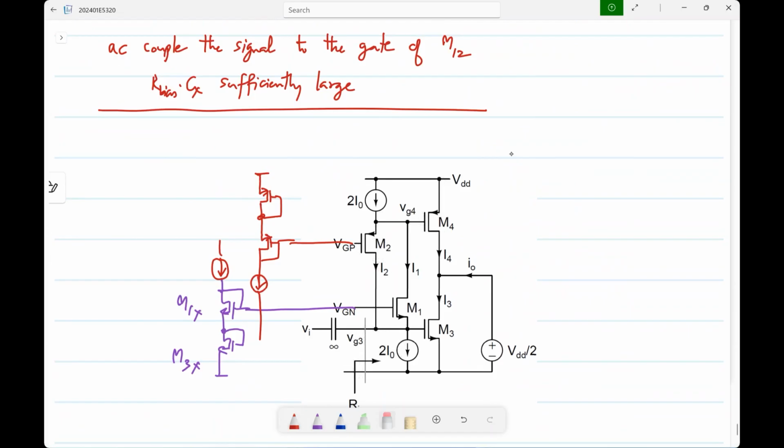I'll continue from there, but I would say this has now fallen out of favor because it's not easy to accommodate all these transistors in a 1 volt or a lower supply voltage. But when the supply voltage was higher, this was used quite widely. This was actually reported in one of the leading journals when it was published in the 80s or something like that. So to make class AB biasing for CMOS opamps.